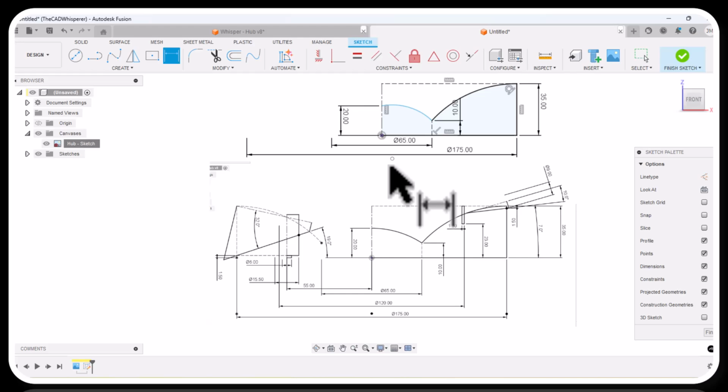And then if I want the center of this arc on that line, I'll do a coincident constraint of this point on that line. And so I don't even need a radius dimension with these constraints and dimensions. Now, if you don't want these tangents, then you have to put the dimensions in there. And so I've completed that part of the sketch.